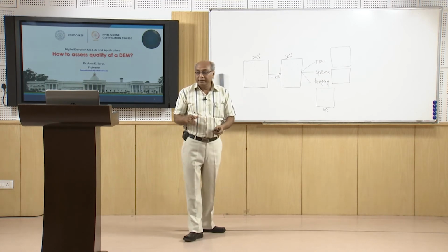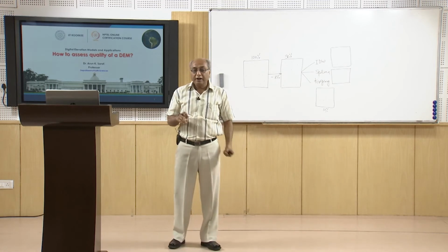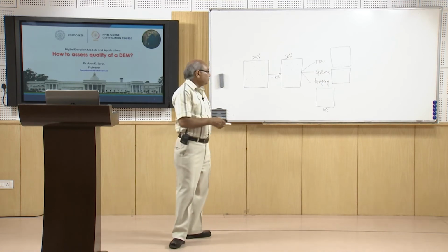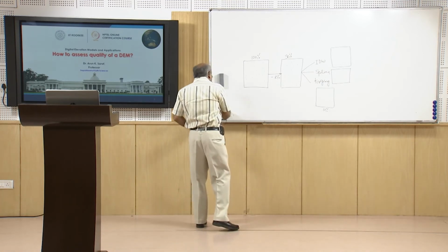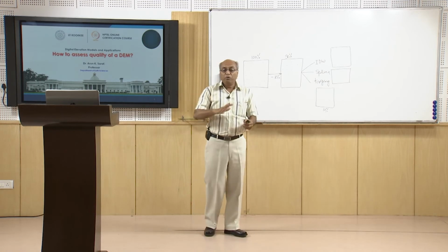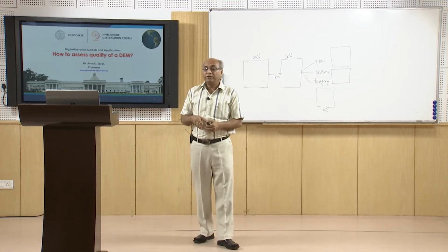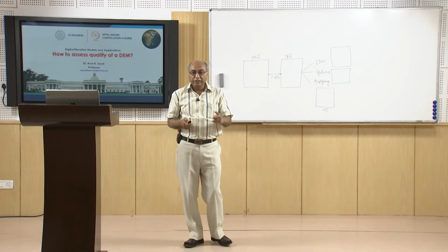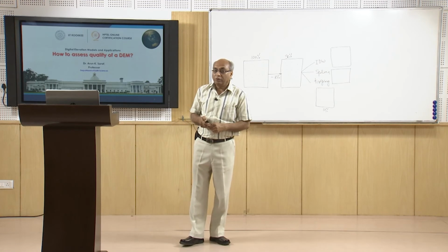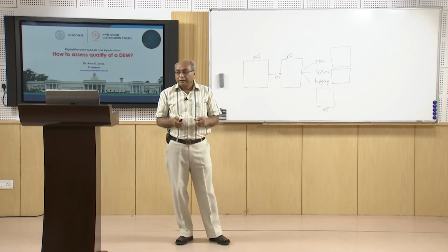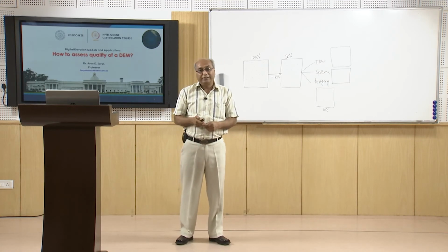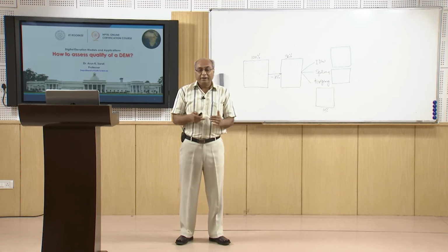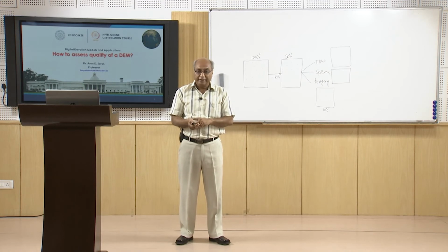So this is what it here means, then, that if we are going for a self-made digital elevation model, then we can first perform this exercise, achieve 2 things together, and then go for using the entire 100% data set and generate the final digital elevation product. In this, we will have full control over the quality of the data set. But if we are using a ready-made data set, then we don't have much choice. We have to live with those errors, but we must know what the inherent errors are.